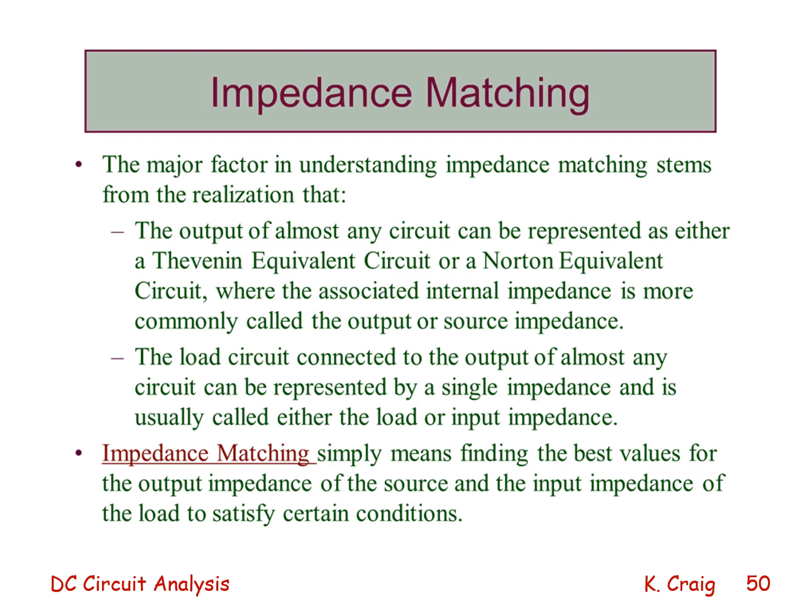The load circuit connected to the output of almost any circuit can be represented by a single impedance and is usually called either the load or input impedance. Impedance matching simply means finding the best values for the output impedance of the source and the input impedance of the load to satisfy certain conditions.